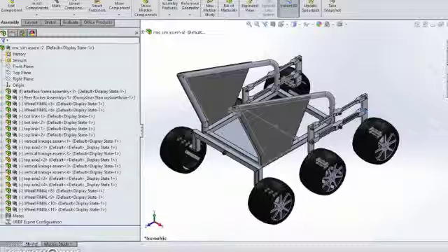With your system positioned correctly and simplified to the point where you want to simulate it, the next thing to do is to think about restructuring your mates. You want to structure your mates in a fashion that makes sense to the kinematic structure of the robot, because the URDF exporter is going to try to read in your assembly to see where the joint axes and origins are going to be. So you might completely delete all the mates of the assembly that you're working on for design purposes and create a whole new set of mates for your simulation assembly.